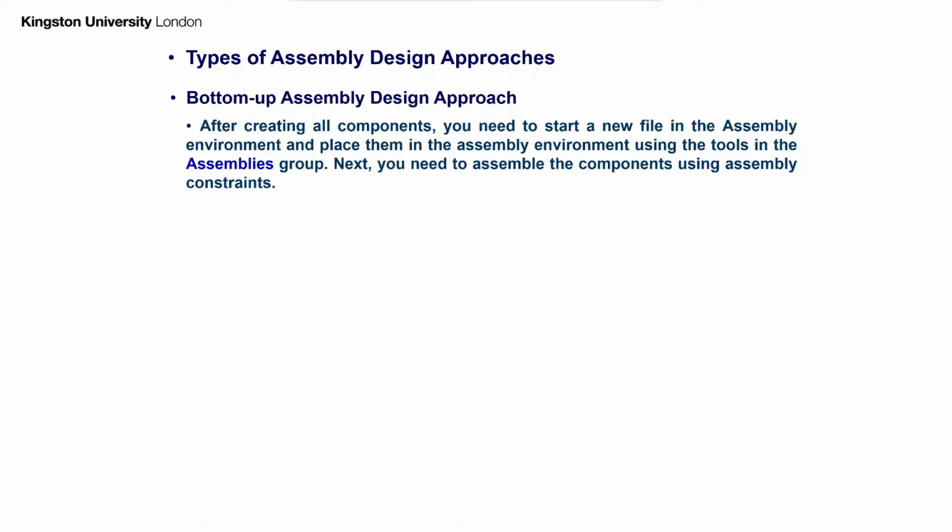Whether we're going to use the bottom-up technique or the top-to-bottom technique. With the bottom-up technique, basically you start with the first component, which is on the bottom of the system or the bottom of the full model, and then continue with the rest of the individual components on top of it. That's using the bottom-up assembly. It's quite well done, and usually we use this method. However, there's a different version of it as well, which basically is the top-to-bottom technique, and with the top-to-bottom technique, you start with the top part as a first part, as a reference part, and then we can continue with the rest.